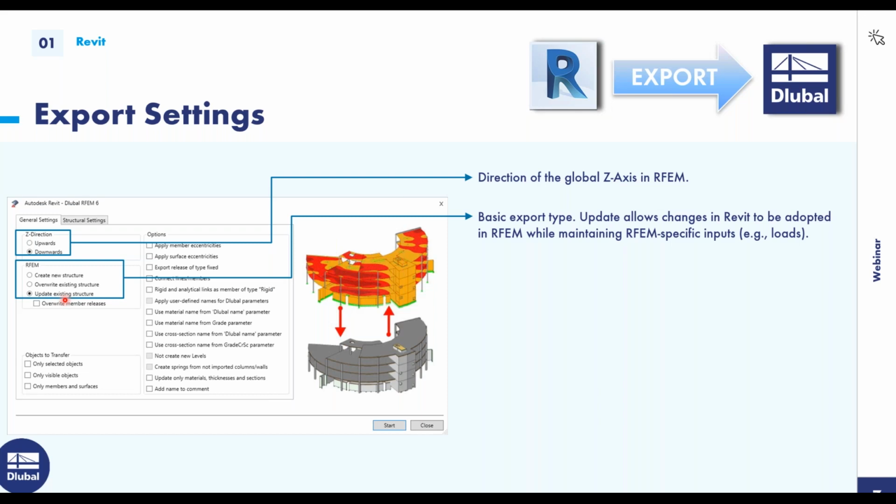in Revit and RFEM. So for example, let's say you first export from Revit to RFEM, and then you modify the structure in RFEM, and then maybe at some point the Revit model gets updated. With this update existing structure option, you can just simply update the RFEM model, and there's no need to start all over in RFEM, and then you can save that.